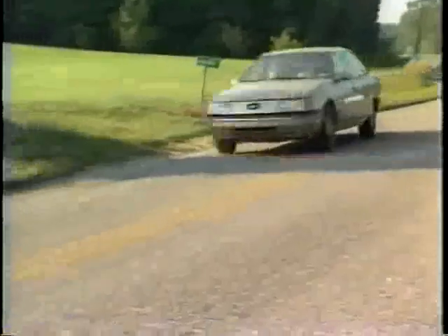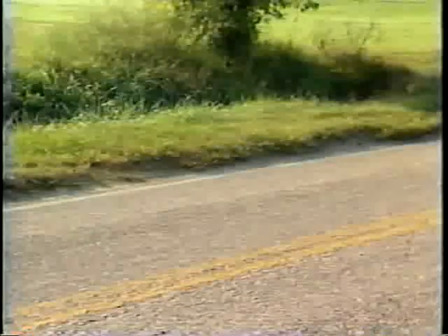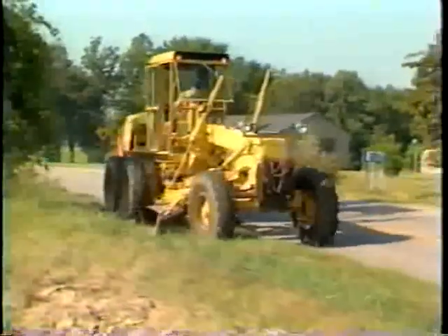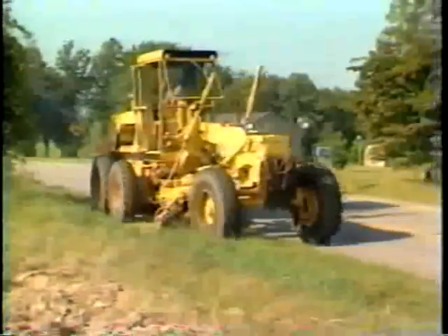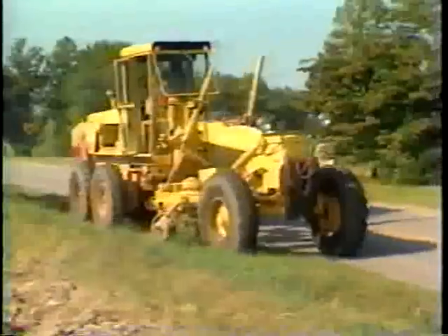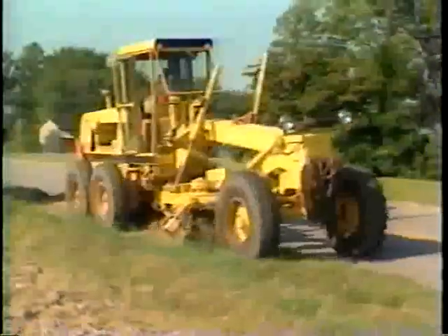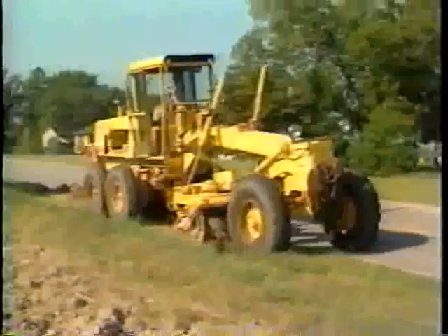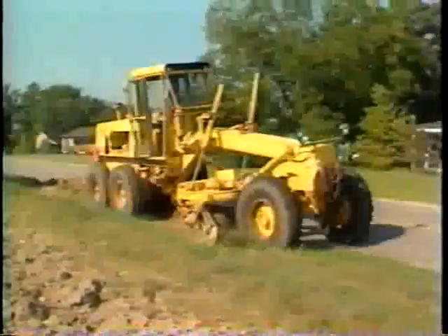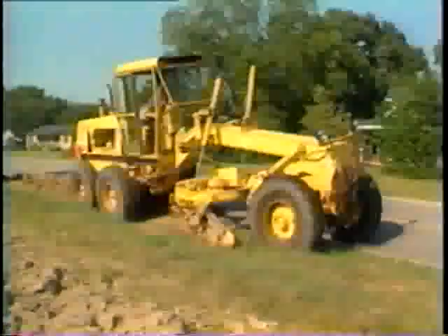The third shoulder maintenance operation is the repair of a high shoulder. Repair high shoulders when material has built up higher than the edge of the pavement. Generally, this buildup is 1 inch or more. In many cases, excess material is hauled away from the work area.